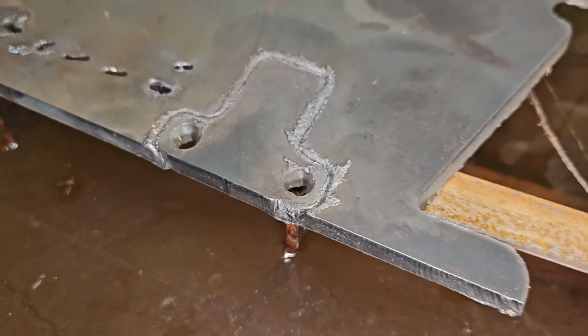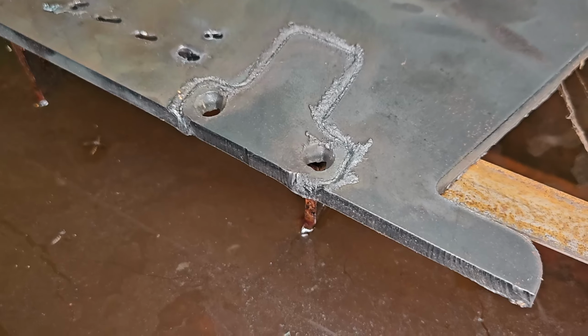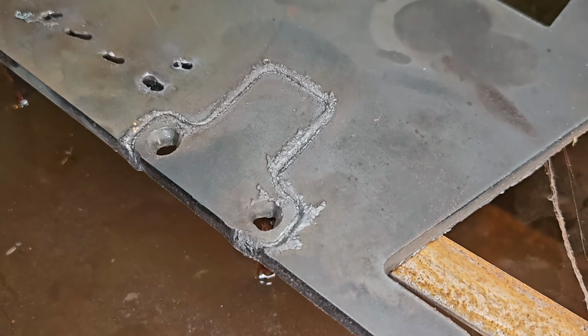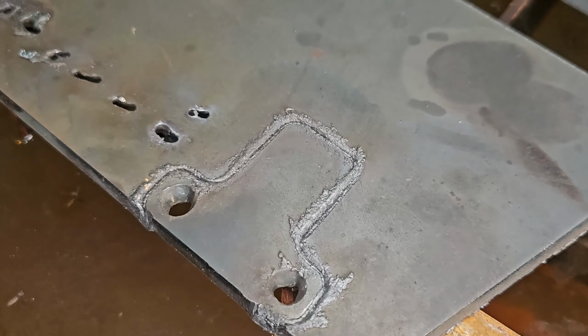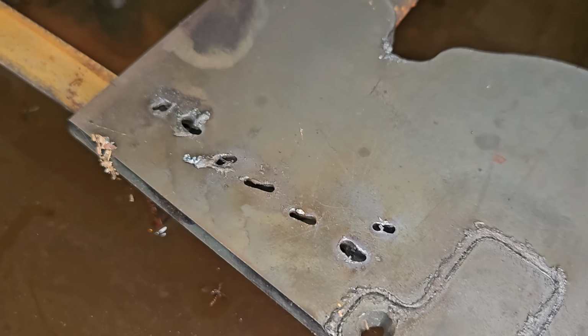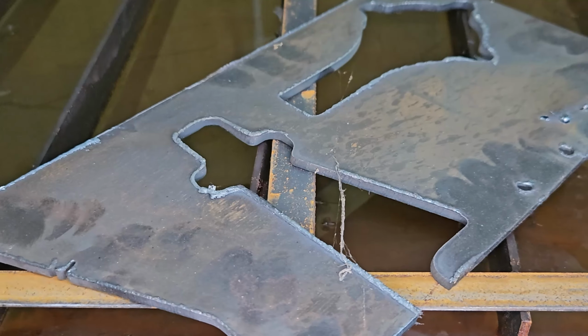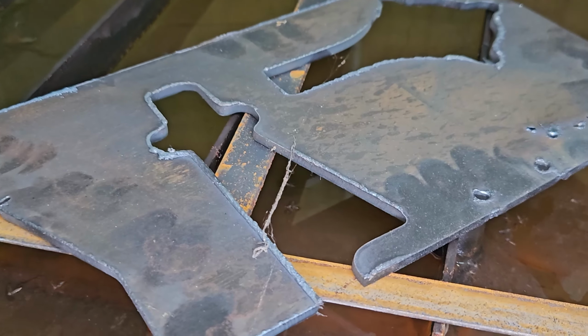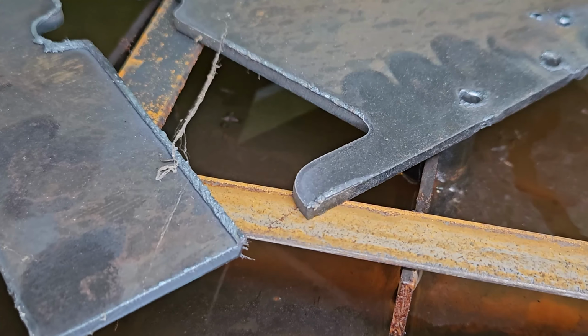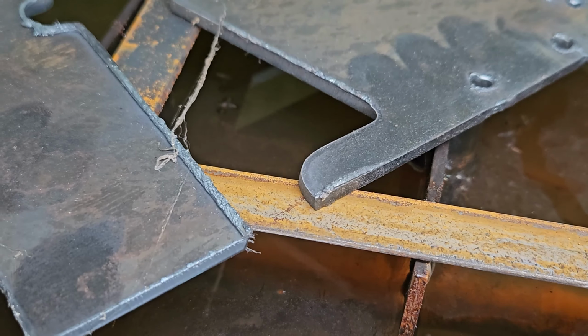Let's now see how these factors work with each other. If you are increasing the arc current, you have to increase the speed. Your compressed air has to be of good quality, because otherwise you will never get anything dialed in. If your torch is not piercing, your cutting speed doesn't really matter. Material must be pierced, so you can take the arc current as a baseline for other settings.